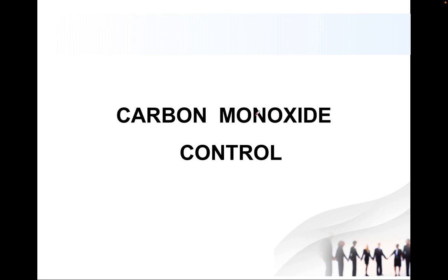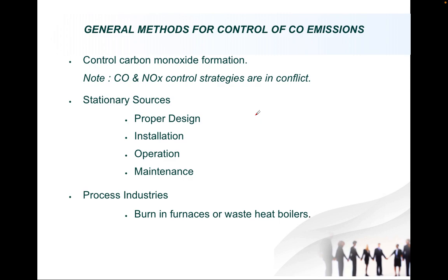One of the simple methods is that we can convert this carbon monoxide into carbon dioxide, because carbon dioxide is not poisonous to human beings. So first of all, why is carbon monoxide generated? Carbon monoxide is generated because of the absence of excess oxygen. Because of incomplete combustion, generally whenever the combustion process happens, oxygen will react with carbon, and carbon dioxide will form. But instead of two atoms of oxygen, only one oxygen atom will be present there, and it will react with the carbon. That will cause the formation of carbon monoxide. So absence of oxygen will cause the formation of carbon monoxide.